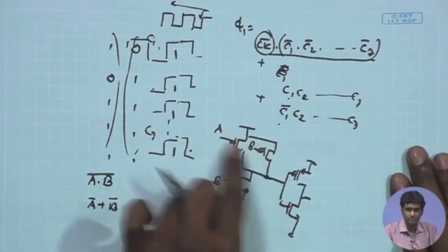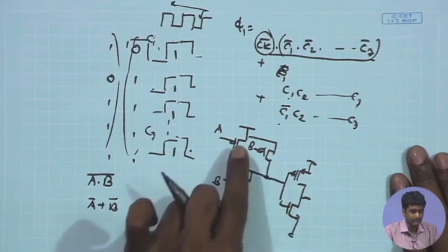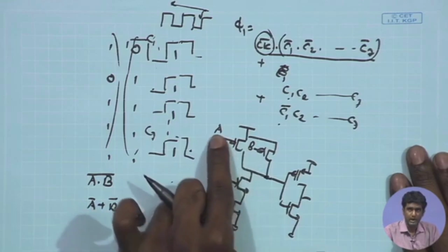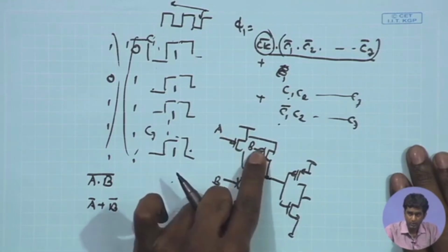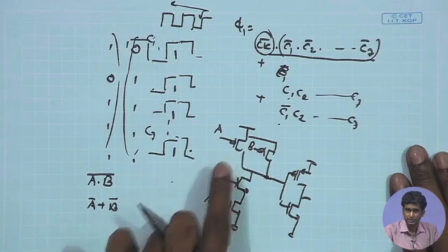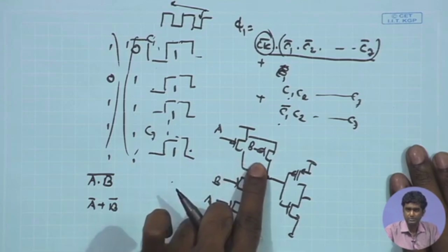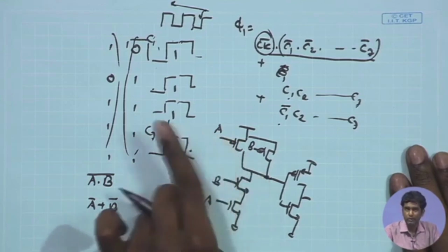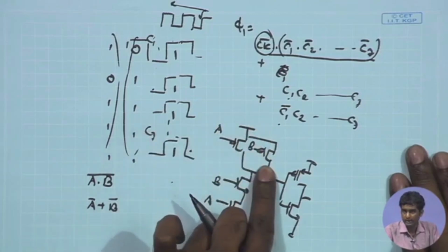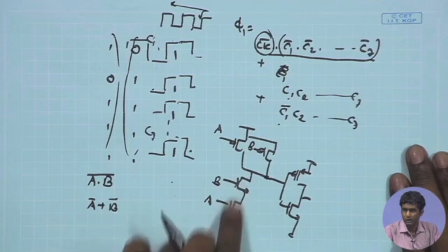So, the PMOS circuitry over here should also support the same logic condition. So, when A dot B is high, then the PMOS should be driving it high. So, then we can see that if you have A low and B low, in both conditions output will be driven high, and that is basically nothing else but this function, right. So, we can implement this A bar plus B bar by connecting A and B transistors in parallel using PMOS, because here when A goes low, this pulls the output high, B goes low, then this pulls the output high.